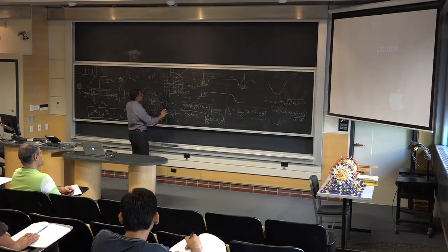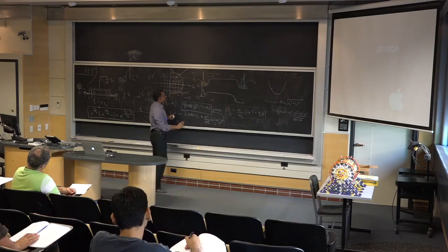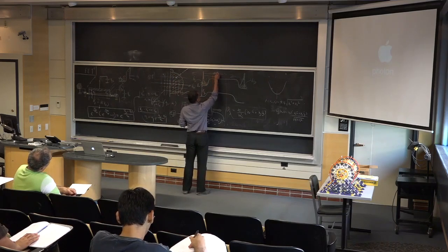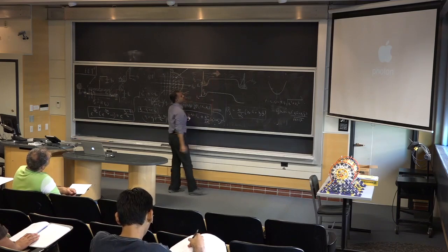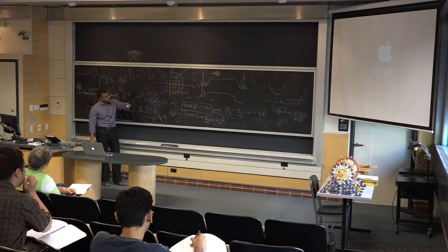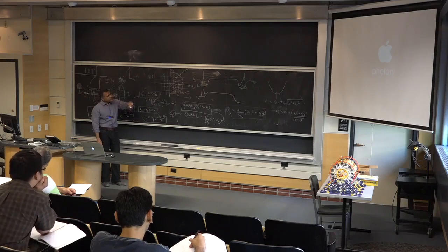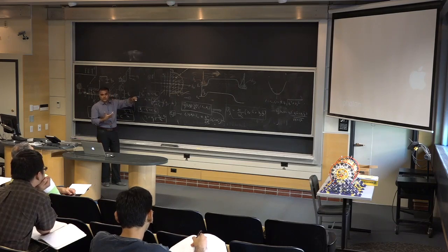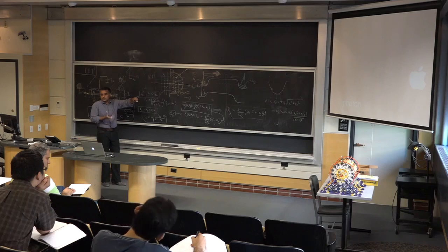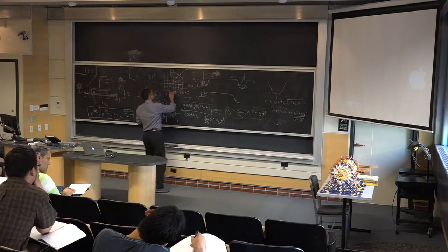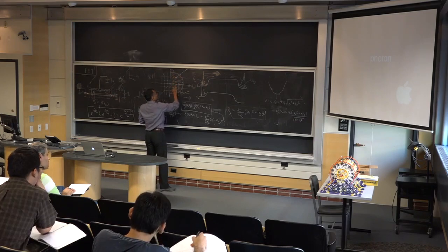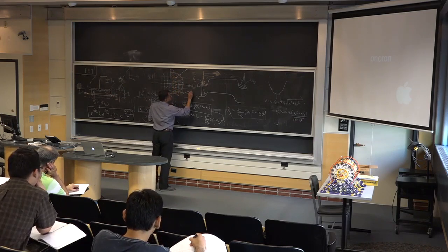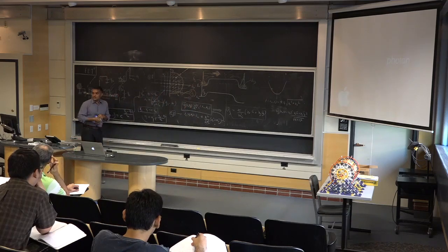But right now we're saying that all these states have filled from the source, or in other words, all the electrons in this ballistic transistor that are moving to the right are moving. There's a chance of non-equilibrium, but they are still in equilibrium from where they started, and that's the source. They're in equilibrium with the source contact. That's the meaning. So what does that mean? It means that the right-going states are filled according to a Fermi-Dirac distribution, but their Fermi level is exactly equal to the Fermi level of the source. The source fills it, and those carriers are in equilibrium with the source.